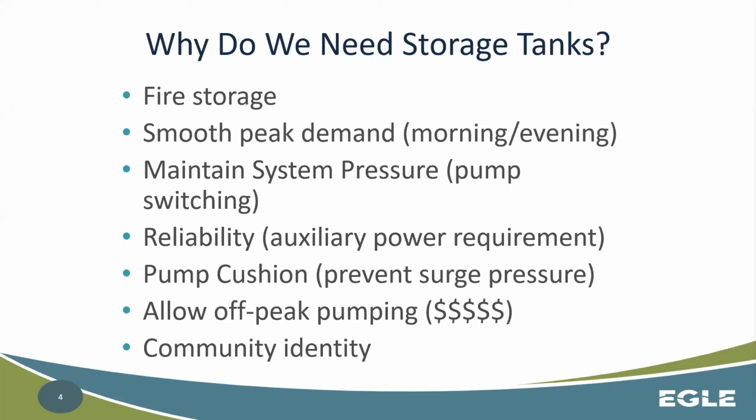Obviously there's the reliability aspect. If for whatever reason a well goes down or a treatment plant portion goes down, you at least have some buffer there, some clean water that's stored, and you're able to deliver it to the system. You also have pump cushion. When the pumps kick on, there's not an excessive surge in pressure throughout the system that might disrupt the water mains or service lines and cause rupturing and breaking of the lines. So it gives a little bit of buffer when those pumps or just pressure in general spikes.